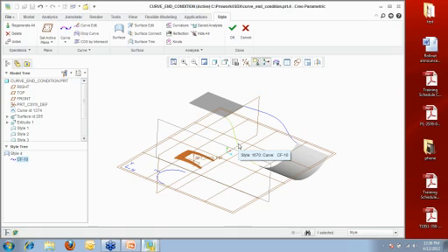If you wanted to use it to define your boundary blend surfaces, you could absolutely do that also. So just because you create these curves in ISDX and use them in ISDX doesn't mean they're stuck within them. You can use them within other features within Pro E.